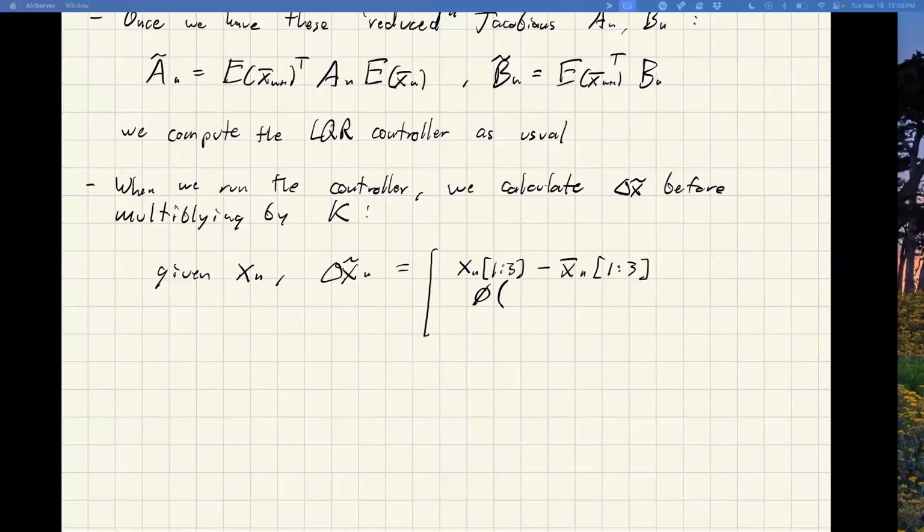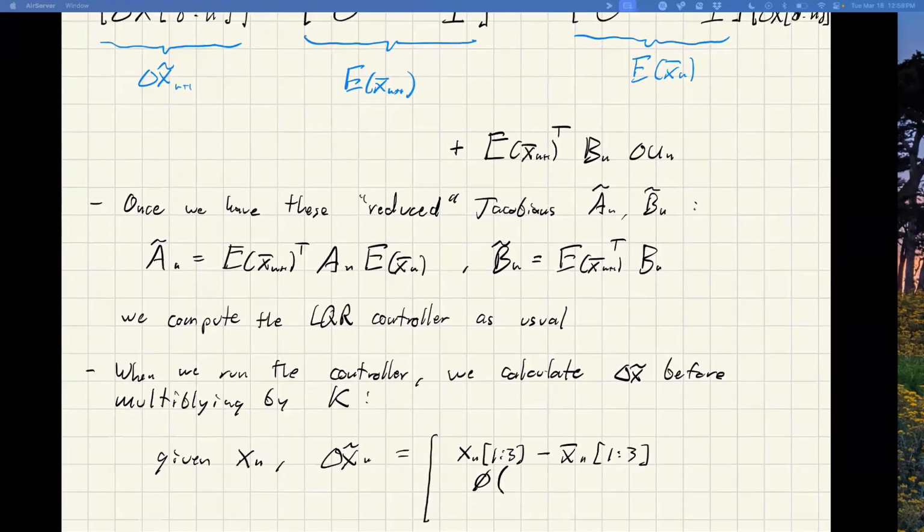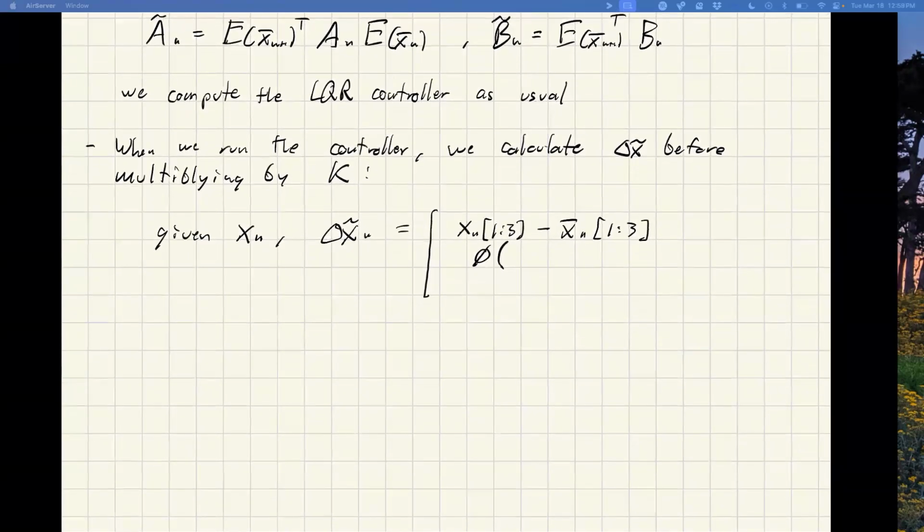And inside there, we're going to multiply the quaternion by the reference and do an on-the-group error calculation. So we're going to calculate the error quaternion that rotates you from where you are to the reference. For us this looks like L of Q bar K transpose QK. That's basically doing a Q bar transpose Q, which finds you the rotation from the current body frame to the reference. I'll write that out in more detail if you want. And then for the rest, we just subtract.